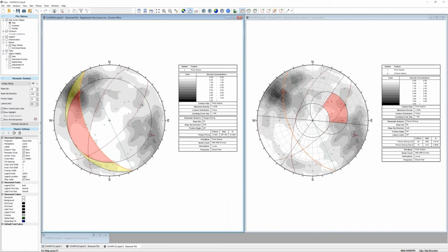On the left, using wedge sliding kinematic analysis in DIPS, we see that the south dipping wedge sliding is the main instability risk. On the right, we have a pretty low percentage of critical poles in the daylight envelope, which would appear to indicate a low likelihood of planar sliding. So how do we amplify the flawed poles that aren't showing up in the daylight envelope, which was evident in the post-failure mapping?